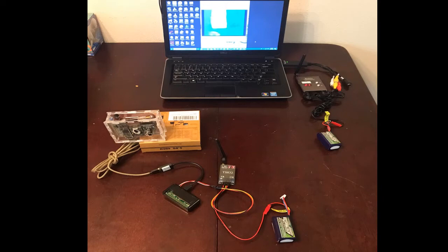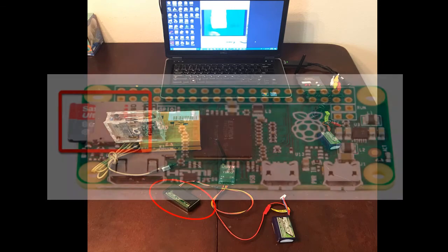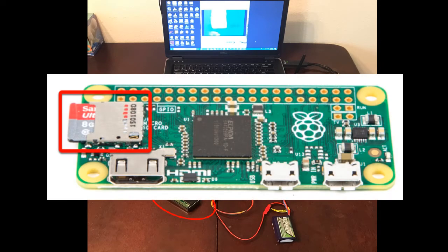The first-person view, or FPV subsystem, is where the communication happens between the infrared camera and the image analytics software. The infrared camera picks up infrared signatures from its camera module and infrared sensor and formats these images as digital. The video output module is made up of a Raspberry Pi Zero that was programmed specifically for interfacing with this camera. This microcontroller has a micro SD card with a full image uploaded onto it, which reformats the camera images from digital to analog for transmission.